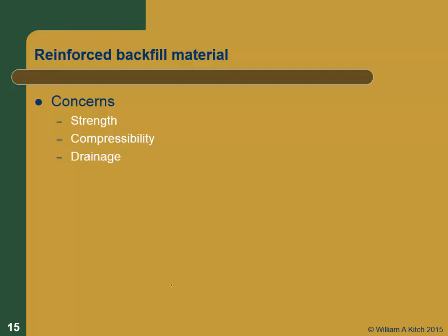It's really important that it be a good draining material, just like with any walls, we really don't want to have water pressures behind our wall. So drainage is very important. And then its durability is important. Just like any of you that do selection of materials for paving, you don't want soils that slake or have durability problems in pavements, because 20, 30 years later you've got problems because there's loss of material, settlement, and loss of strength.